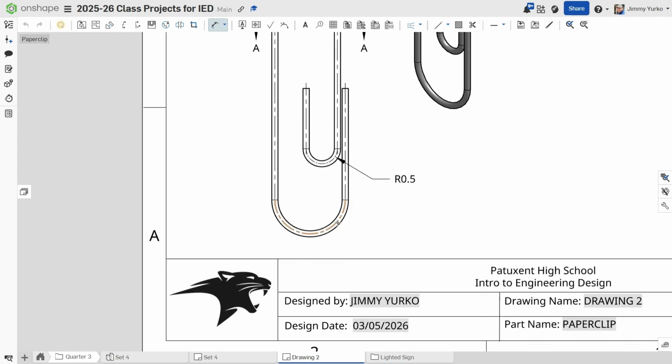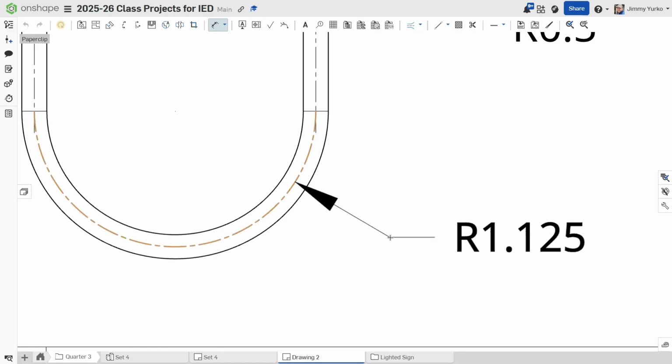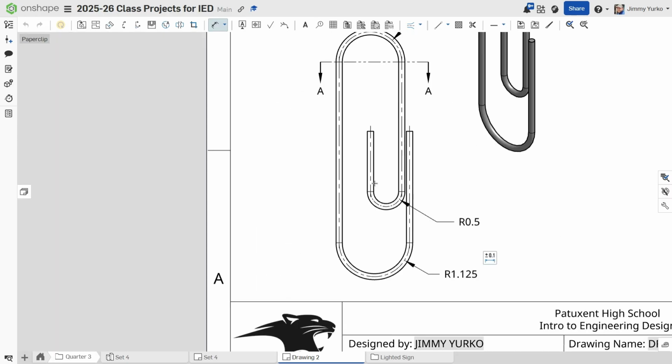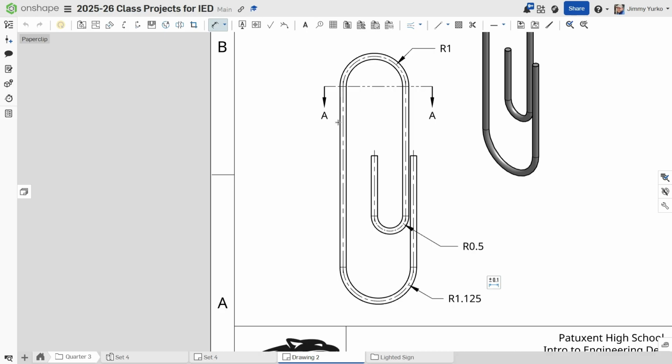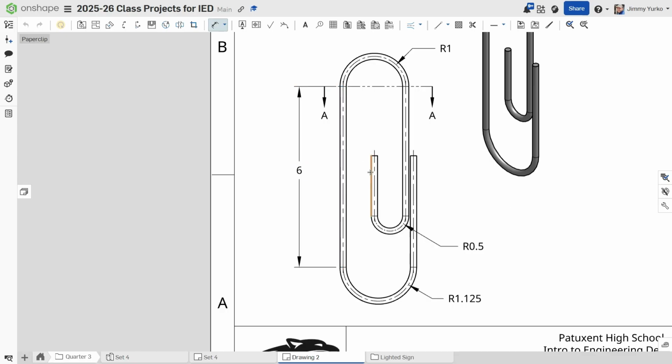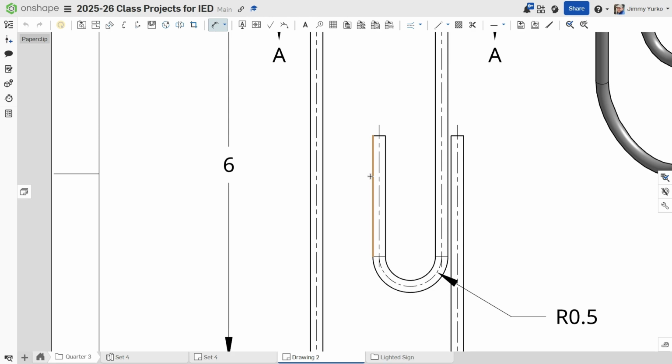And then we'll come down here. Notice that I am clicking on the center line that we added, not the edges of the model. So if you're not getting the same model dimensions that you typed, you may be selecting the wrong item rather than selecting the center line. Like right now, I'm going to select this edge, which is appropriate because I want the length from this point to this point. But in the arcs, you want to make sure you're selecting the center line.